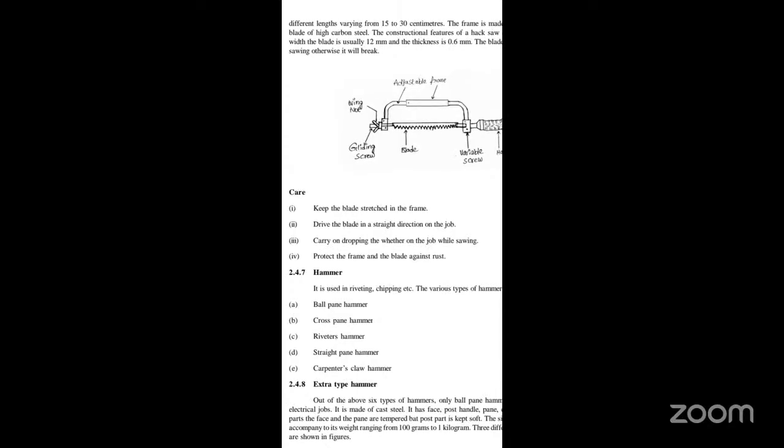Next, care. Keep the blade stretched in the frame. Drive the blade in a straight direction on the job. Keep dropping water on the job while sawing. Protect the frame and the blade against rust. These are the care points required for this instrument.